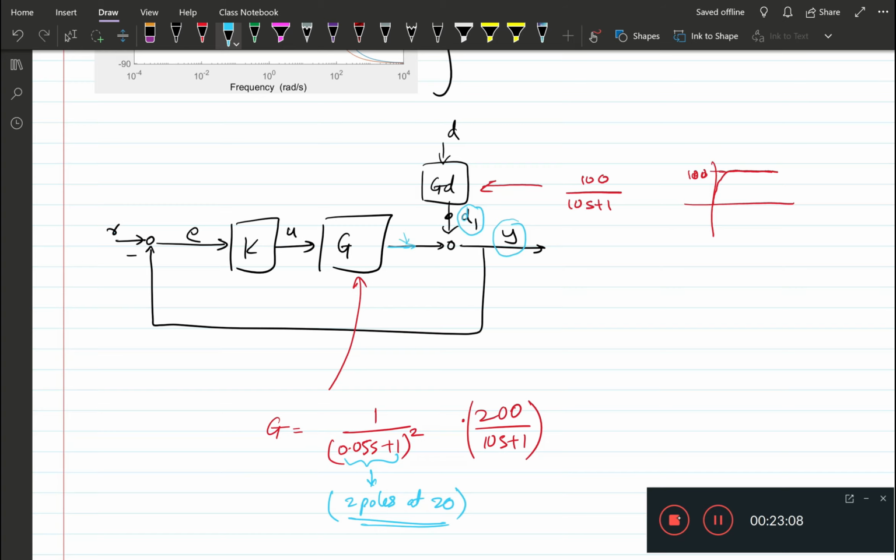In the case of the disturbance, the controller starts seeing an error which is growing from 0, and as the D1 is increasing, the error is increasing. So the controller does not see a spontaneous non-zero error, whereas in the case of the reference step, the controller sees a spontaneous error at time 0.